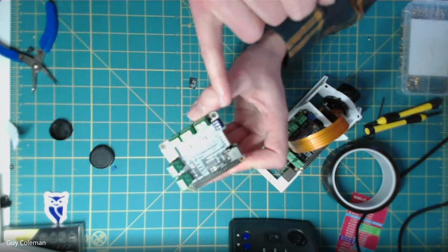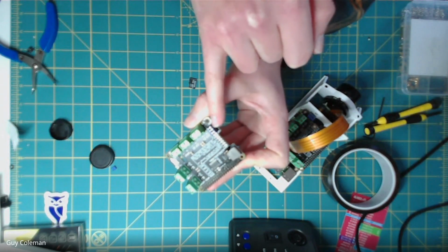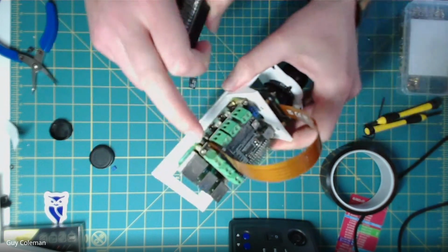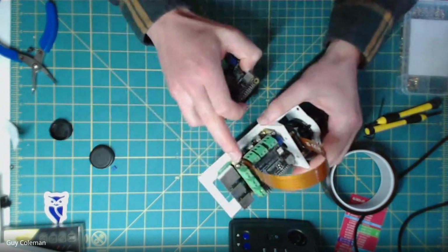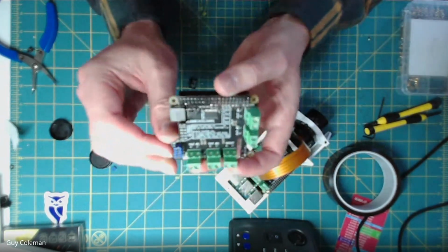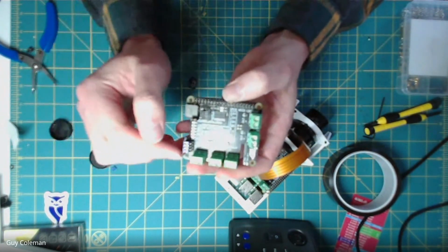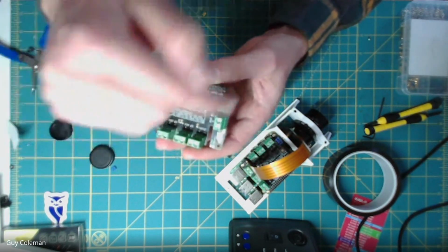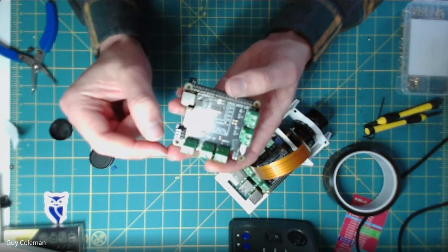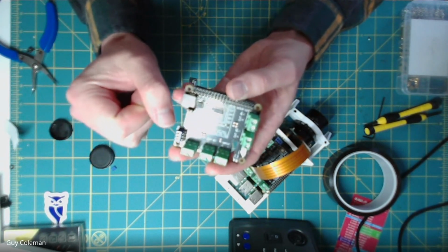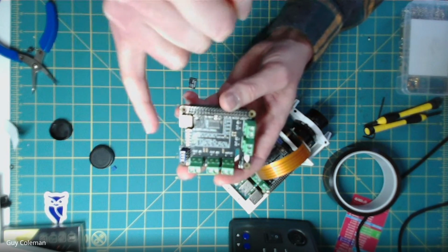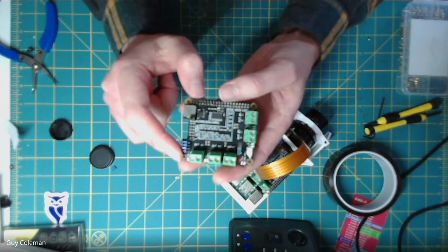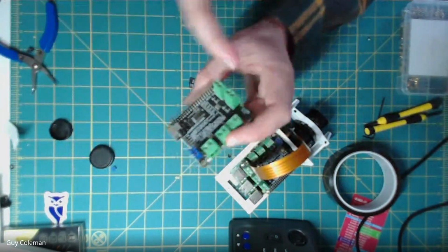What you can see here is there are a set of 4 jumper pins here, and there's a set over here, and on this one there's a set of jumper pins here, which is for the enable. Going through them, these sets of 4 or 6 let you choose how you want to control each of the outputs. At the moment, by default, they're all set to the GPIO, so the Pi. If you have them over to the right-hand side, at least for me, that will let the Pi control them with the default GPIO pins. And the default pins are described just here.